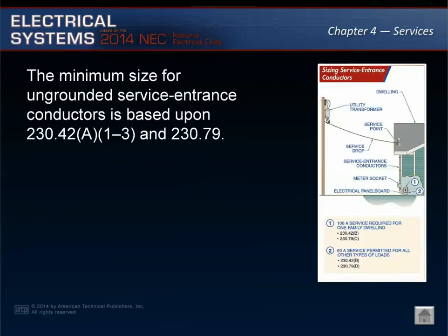The general rule for sizing service entrance conductors is that the conductor shall have an ampacity per Article 310.15 that is suitable for the computed load. The load for the service entrance conductors shall be calculated per Article 220.